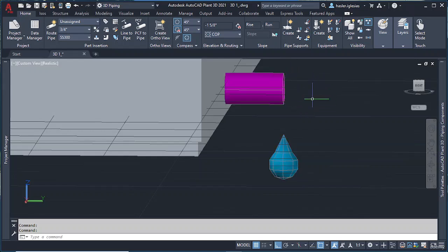When it's open. If I add something here, let's say an equipment, and I think it's connected, but I see this drop, it means that even though it could be visually connected, it's not appropriately connected. So there is no data that links the pipe to the equipment I'm looking at. So you have to be very careful, and it depends on what you're drawing.